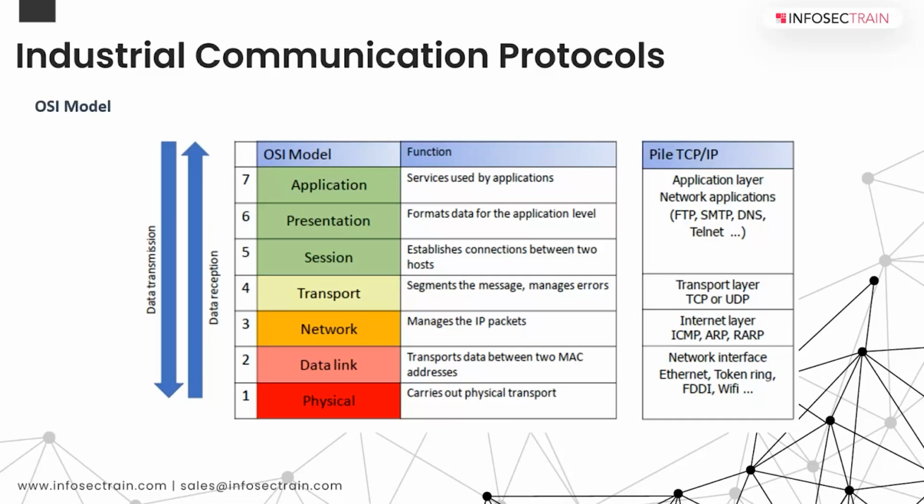So, like I was saying, at higher levels, especially level 1 and level 2, it is necessary to transmit information between the various processing units like PLC, RTU, and the supervisory control system and so on. Different types of protocols are Modbus, Profinet, Ethernet IP, OPC UA, Unified Architecture, that's more recent. And this data transmission is usually carried out by Ethernet.